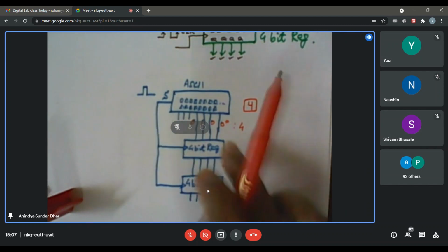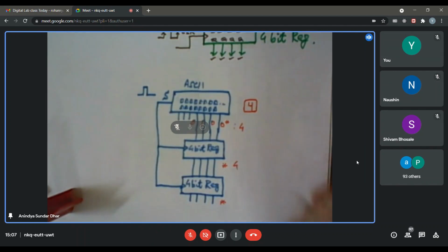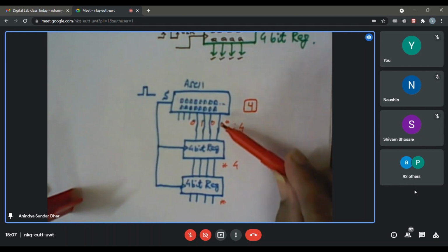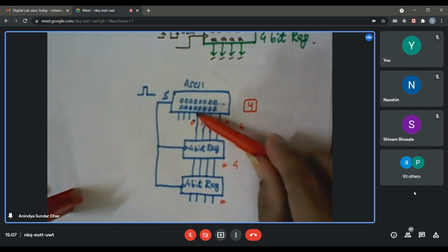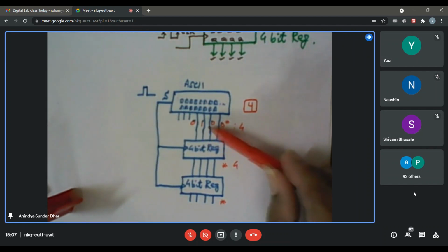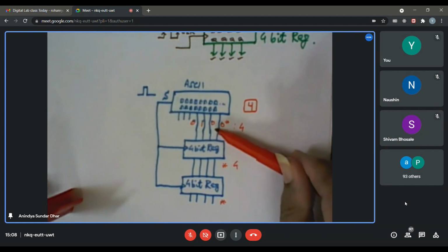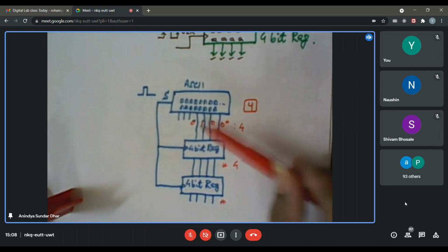If you release the key, at that time it is being generated. So it assumes that you keep it for a sufficient amount of time so that the output is stabilized. Otherwise, as soon as you press the key and the strobe signal is generated, it may so happen that it takes a little while, even a few tens or hundreds of nanoseconds later than this edge, and then this register will not be able to capture that. So it is important to generate the strobe signal after the output stabilizes.